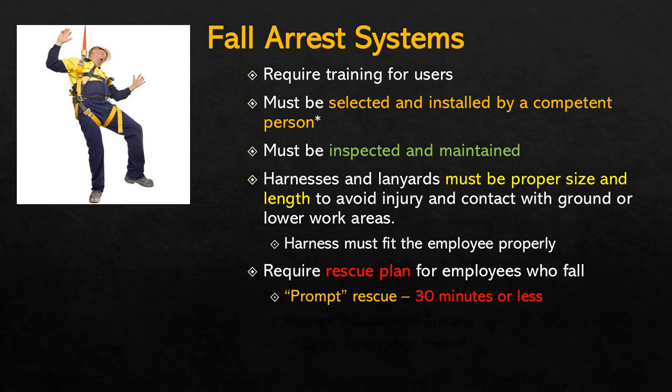Fall arrest systems: you can't just leave a person hanging. Literally, you cannot do that. There has to be a rescue plan in place as well for employees who fall. A person who falls over the edge in a fall arrest system, they can't just be left dangling.